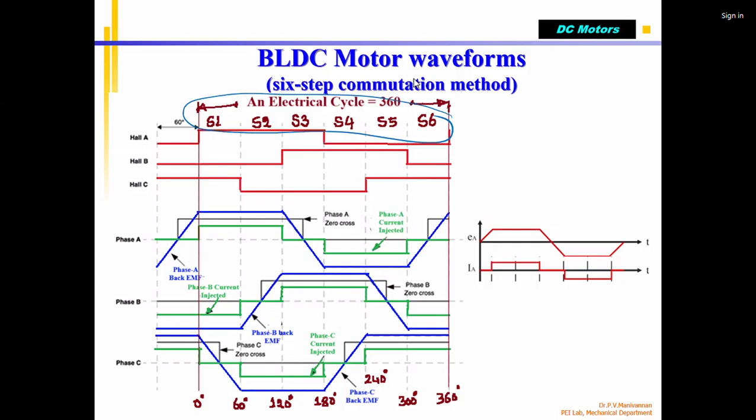So by doing this, I can generate, based on this signal, the stator supply voltage. Then it is called Hall effect sensor based control. Instead of that, if I use this, it is called the back EMF based sensorless control.